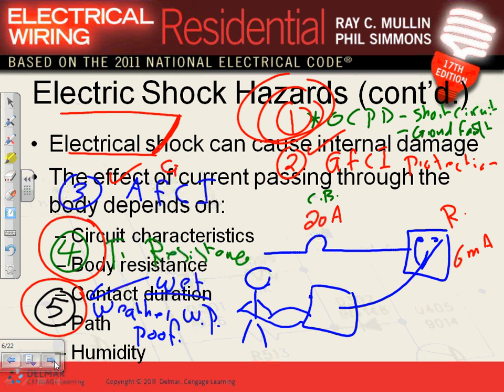And of course, if this is 120, imagine if this voltage is 480. If I grab one phase here and one phase here and grab on them, with 480 in both hands, that will send you immediately to the second life. You are acting as a single phase motor between two phases. So that's what it talks about, the characteristics, guys, the contacts, and the path that goes with it. Like they said, going from hand to hand through the heart, done, completely done.